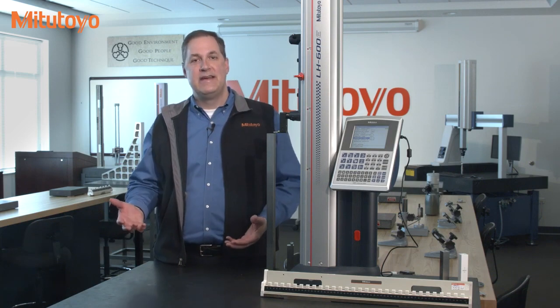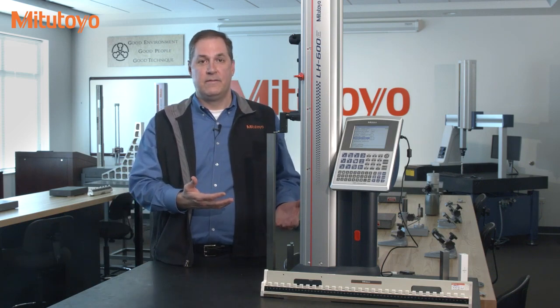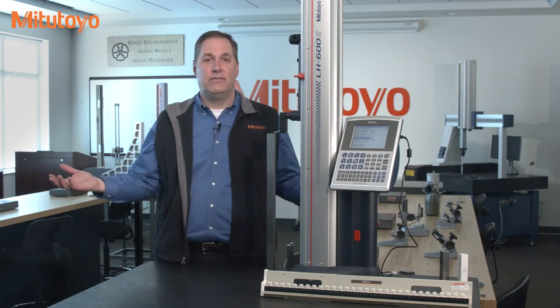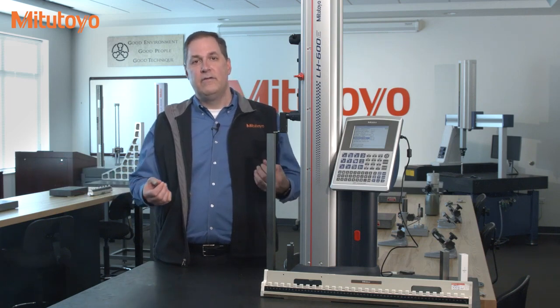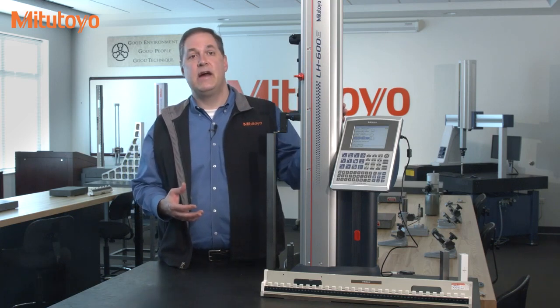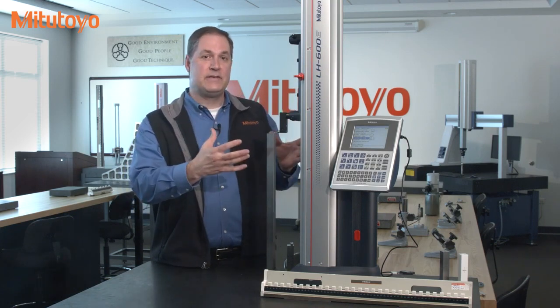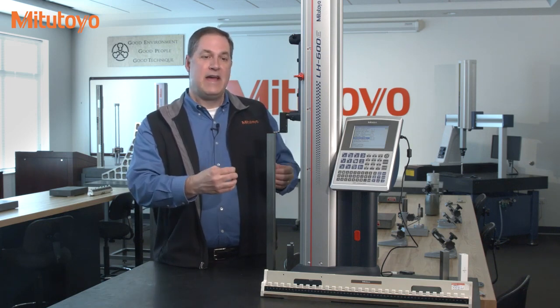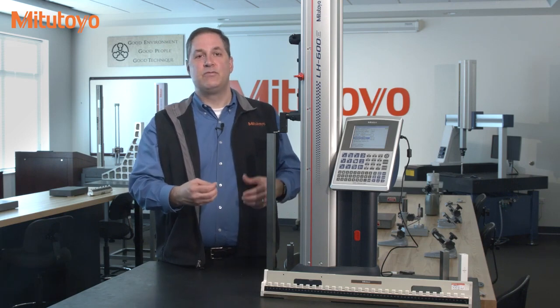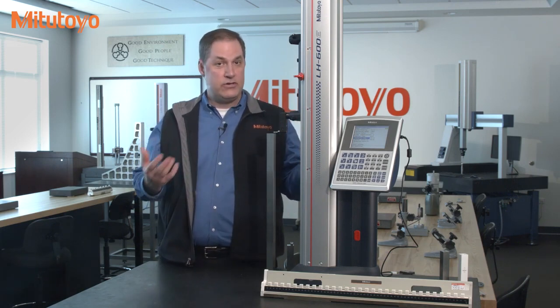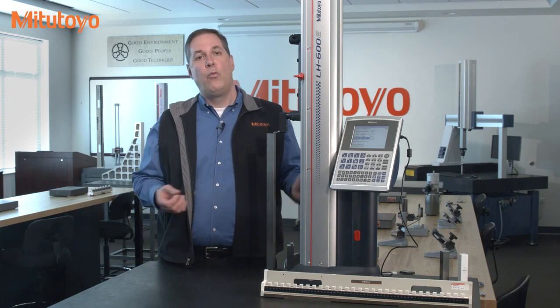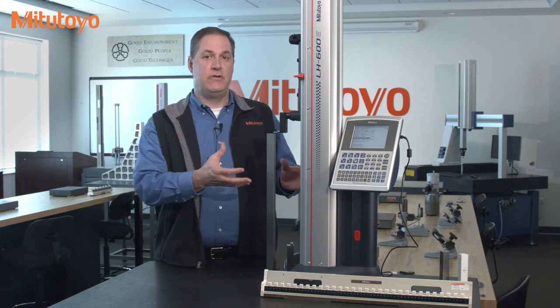When I said that temperature impacts all measurements, this is what I was talking about. So what do you do? Well, now you can understand why this unit has built-in temperature compensation. Its purpose is to automatically correct this exact error that we're talking about. For measuring systems with temperature compensation, you should use it. Without temperature compensation built into the units, you have two other solutions.